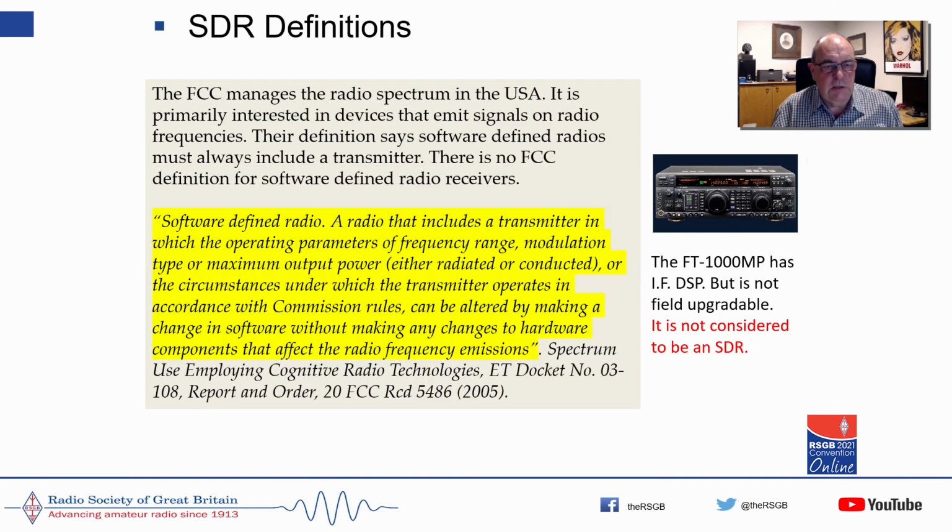And again, they're saying that as long as you can change some of those things in software without actually affecting the hardware, then it's an SDR. Clearly, that's not what we describe as being an SDR. For instance, the FT 1000 MP, it's got IFDSP, but it's not field upgradable. You can't download a new firmware to it. It has to be done by taking the firmware chips out of the radio. So it's not considered to be an SDR.